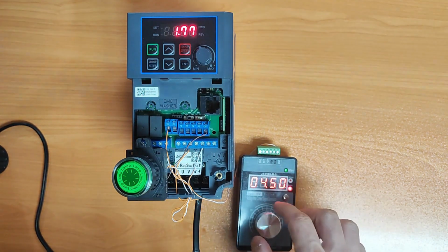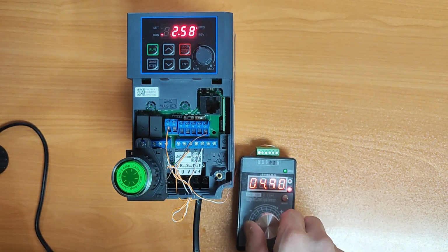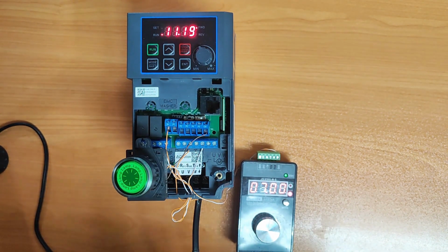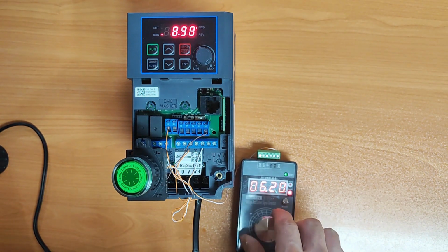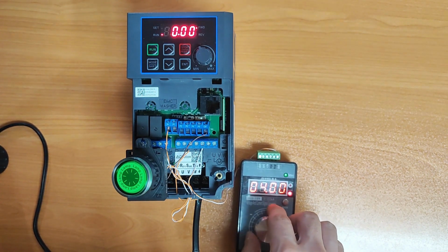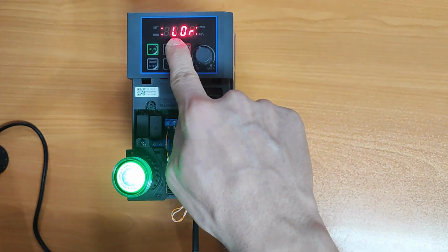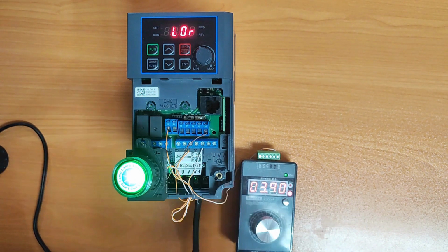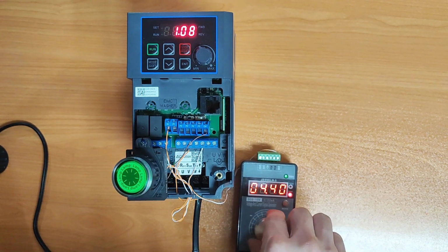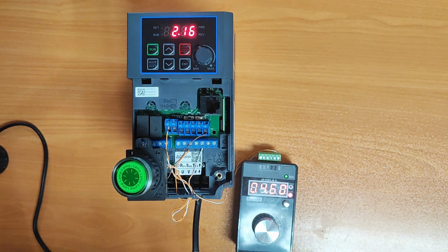Okay, I'll start the inverter now. You see my analog input is 4 milliamps. Now I'll increase it. It's 7 milliamps. If my analog input decreases and drops below 4 milliamps, 3 seconds later, the inverter issues the speed command lost error and free runs the output. Now my analog input dropped below 4 milliamps. 3 seconds later, the inverter issued the lost command, my relay activated, and my signal light turned on. I'll increase it again. As soon as it increases, my lost command error disappears and my signal light turns off.